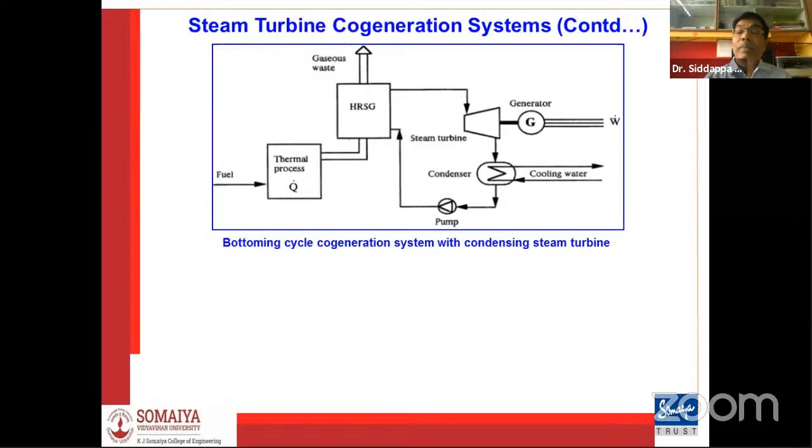Then the pressure requirement in the boiler and the input temperature of the exhaust gas play the role in how much pressure of steam you can generate in the boiler. Depending upon your requirement of steam pressure and quality of the steam, you can change the operating parameters as well as the device also. Or if you want more pressure and you have less potential heat energy, then you can use low latent heat type of evaporation fluids other than water. We are using compounds like toluene and other things which evaporate at a lower temperature.